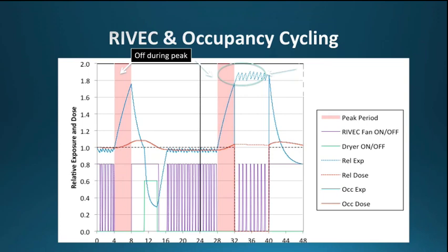So after the 4 hours, the controller turns on again, and it sees, oh no, we're way too high, so it turns on the fan to full power for what ends up being about 6 hours, and starts pulling those numbers down again.